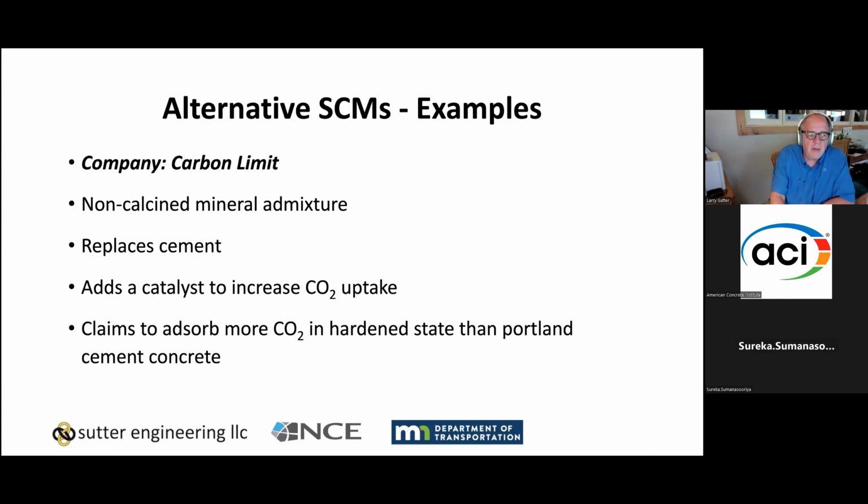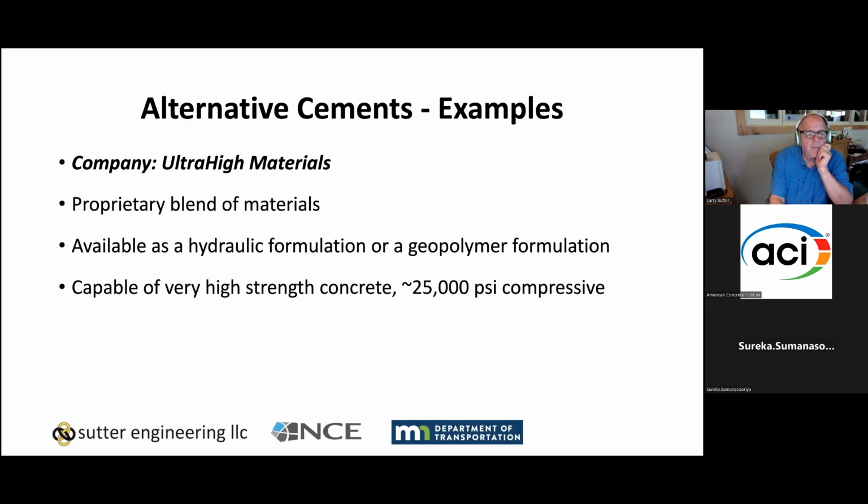Carbon limit, as I said, has a non-calcined mineral admixture that has a catalyst in it that increases CO2 uptake. So basically it is used as an SCM and it performs like an SCM, but then once the concrete is hardened, it is going to have a higher rate of CO2 uptake than Portland cement concrete.